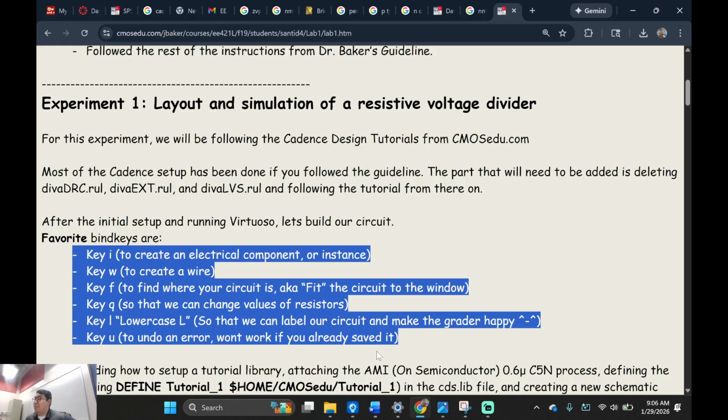Let me tell you this about industry, and I get this question asked a lot. I'm working with one of my best buddies, an IC analog designer for a good 10 years. His biggest complaint is that people aren't practicing Cadence enough. And by practicing, he says, just mess around with the body effect of the transistor. Design some funny telescopic op amp, or maybe a PLL, a phase lock loop, or something little and cute. Just little circuits, okay? Just investigate your own circuits.